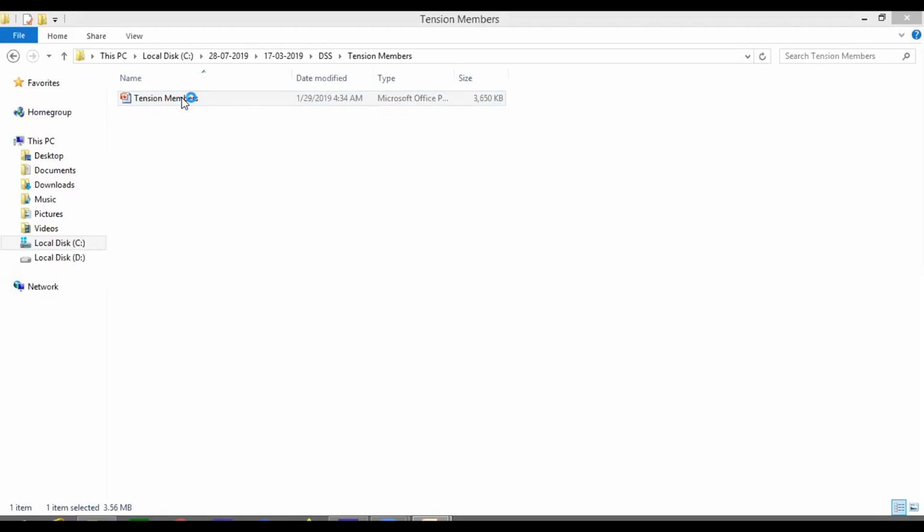You can go through this again, or else you can go through my PPT, my lecture on Facebook, where I described and explained clearly how to calculate the net effective areas for different kinds of critical sections. It is for zigzag sections, for chain connections, staggered connections, even for diamond patterns. I have calculated the net effective area for the different critical sections.